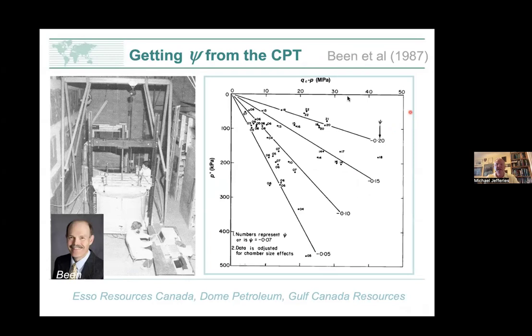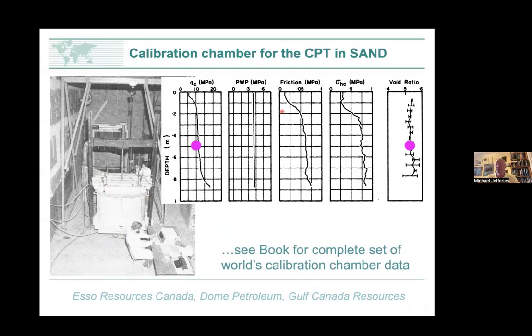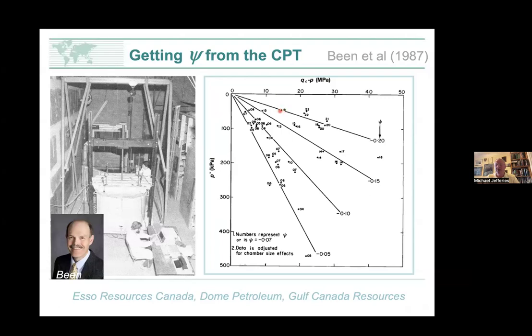So what I have on here is, and that's my colleague Ken Bean, because he was the guy who cooked up this chamber test, each one of those dots represents one of those tests. The dot represents the tip resistance we've measured and the confining stress. There, we've done it in terms of mean effective stress, and the number is the state parameter for that test. In fact, to make the graph easy, that's actually minus 0.18 as a state parameter.